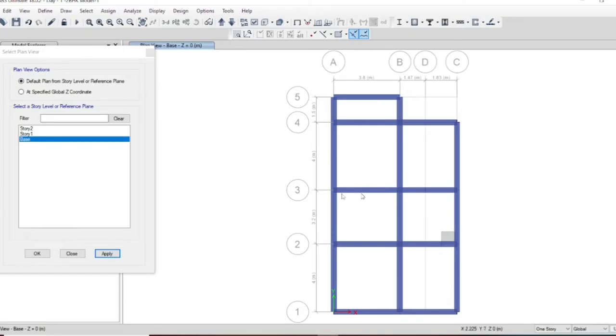Now you can see wind is flowing in this direction or in the y direction. We do not know in which direction the wind is going to blow. So what we have to do is apply all the sides. All the four sides you have to consider separately, and you have to apply wind. Wind can flow in one direction for some months, and wind flow can change to another direction for some months. So you cannot take only the x direction and find the critical force for the analysis. The wind might flow in other cross directions also. So you have to take all the sides as your wind cases to find the maximum force.